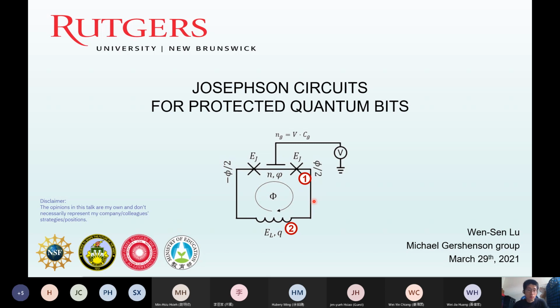For example, in the transmon qubit, we change the EC over EJ ratio to suppress the slope of the charge dispersion curve in the transmon, so we have charge insensitivity in T1. In this case, we get advantage by inserting extra elements to get accidental degenerate levels in the Hamiltonian in order to provide additional layer of protection.